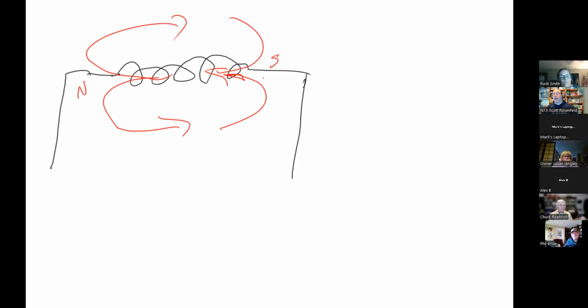Well, now we have no battery, and all of a sudden this magnetic field is sitting there in space, and it hasn't permanently magnetized anything, and it's like, okay, I've got all this energy stored up. What am I going to do with it? What ends up happening is that this magnetic field tends to create a high voltage right here across the coil, and it says, okay, I have to get rid of this energy somehow. And what it does is it generates a really big voltage right here and causes a spark to jump across it to dissipate the energy.